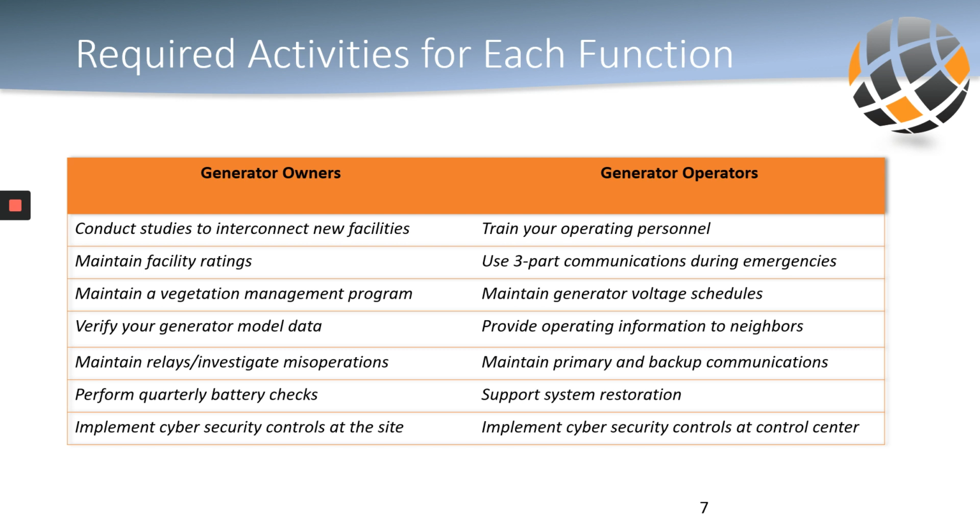Generator owners and generator operators are required to perform different types of activities for a generation facility under the NERC standards. For generator owners, this includes performing interconnection studies, maintaining facility ratings and a vegetation management program, verifying modeling data, maintaining relays, and performing battery checks on defined intervals.